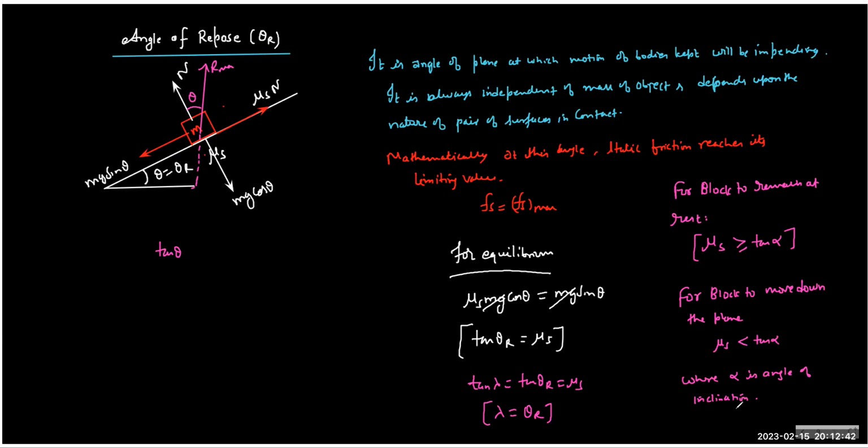So that's very interesting that every heap formation in nature, whenever you pour anything, if you pour salt, any powder form, even a bigger object. So let's say you start pouring pebbles. Or not only that, if you have anything loose, let's say sand or soil, if you start pouring, it is always the conical heap. And this conical heap is because of the friction force actually. So it is friction which is stopping the fine grain from falling further. Okay. And that is always there. So this angle of repose is a very interesting idea, and we do use this idea for a variety of situations. I'll show you one example.